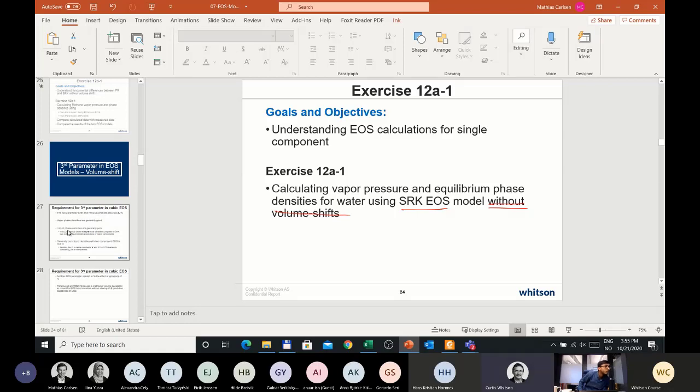Hi, yes. There are some scenarios where we have a transition to dense phase. In that case, which one is recommended, or which one is better? I think both SRK and Peng-Robinson will have equal issues with handling dense phase transition, right? So in that case, what would be the advice? For water? No, not for water, for the hydrocarbon mixture.